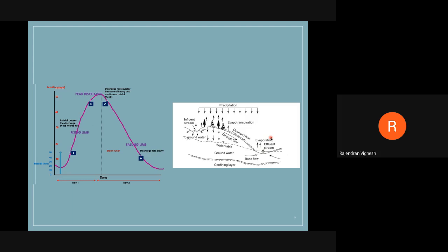So the first thing to understand is the hydrograph. What is a hydrograph? It tells about the total process: what rainfall is happening, how the water becomes available on the surface as well as underground, and also the losses. We studied the initial losses like depression storage and interception. You add up everything, and that is this hydrograph picture. Now I don't want the details about the initial losses, so remove them, and also the water going under the ground. I need to know how much water is available only on the surface. So I have removed the initial losses and the base flow.